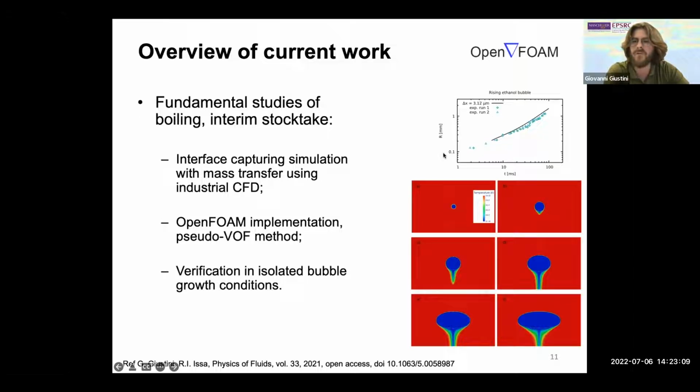So here, I'm using a log scale in this plot on the right. So maybe the actual results are not as good as they look, but still, between the solid line that represents the equivalent bubble radius from CFD simulation and the various points that represent experimental results, there seems to be good agreement, provided that we're using very fine meshes, because here you can see we're using uniform meshes with cells of a few microns, whereas my bubble is something like 1 or 2 millimeters in radius. So here we're talking about very fine meshes compared to the bubble characteristic dimensions.